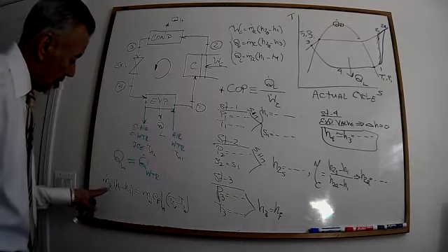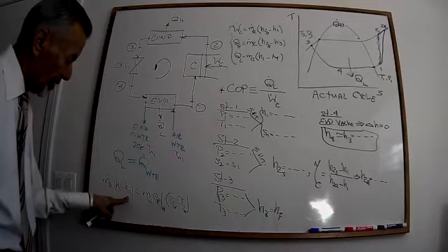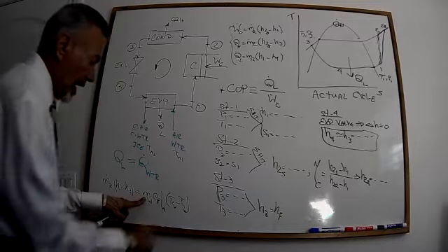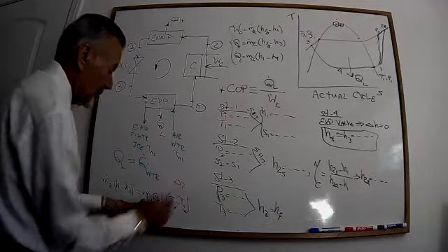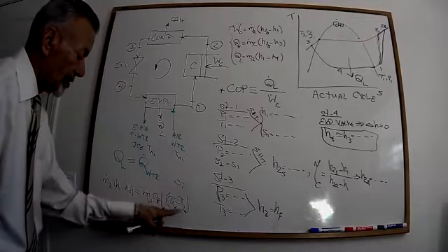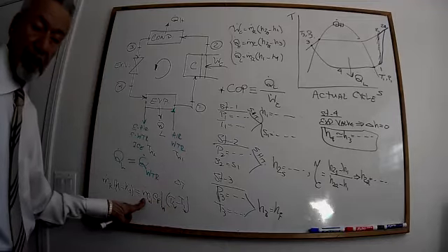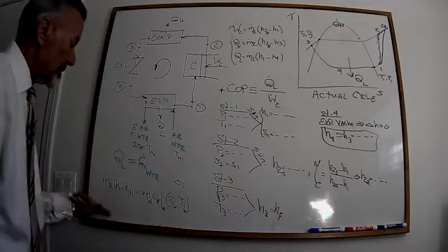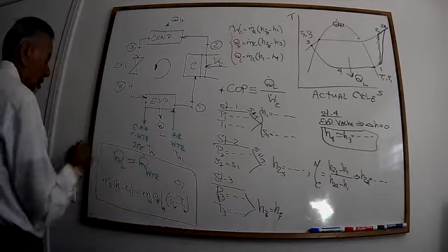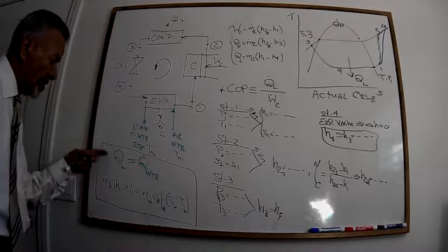So if you already have the mass of refrigerant, you already found H1 and H4, you can have the mass of water, and they ask you to find the delta T. Or they give you delta T, they give you T2 and T1, and they want you to find the mass of water. So this relationship will make things work. So watch out for that.